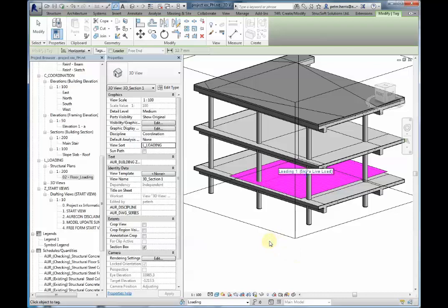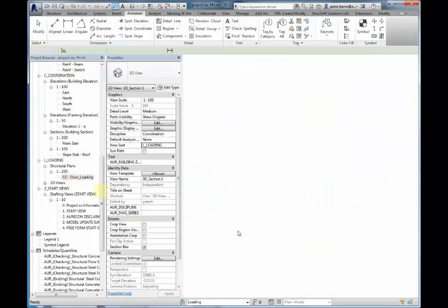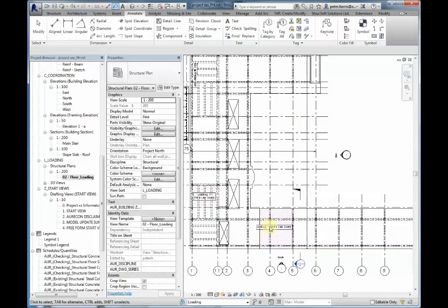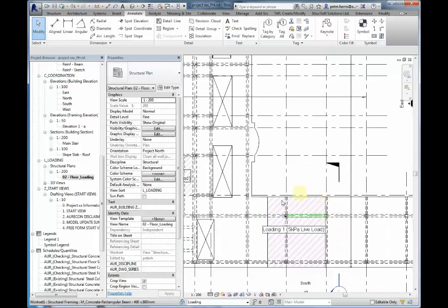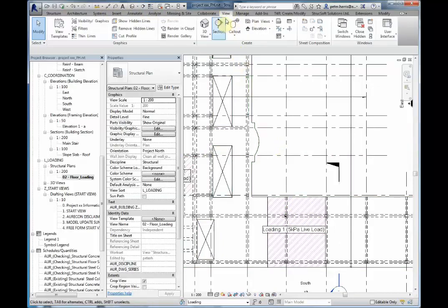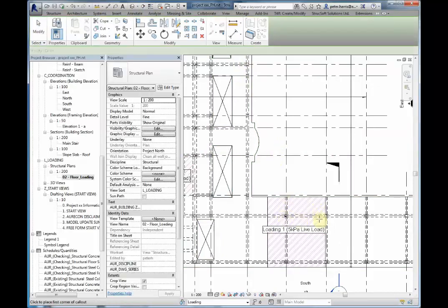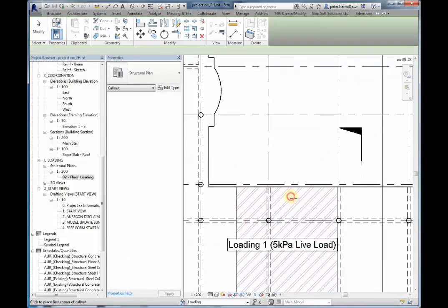And the final requirement is to create a matching legend. So to do this, because it's a live active component, we need to, off our plan view, create a callout. Under the View tab, doing ourselves a callout. Certain size.